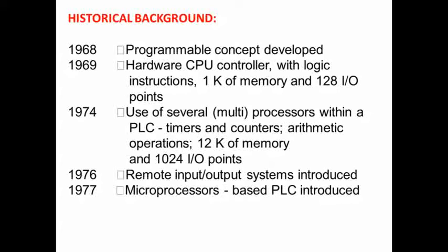It can be program controlled and operated by a person unskilled in operating a computer, but who is PLC literate. The PLC operator develops a ladder diagram, which is then converted into computer machine language and runs as a user program. There are some advantages of this PLC system, but we will discuss them later.